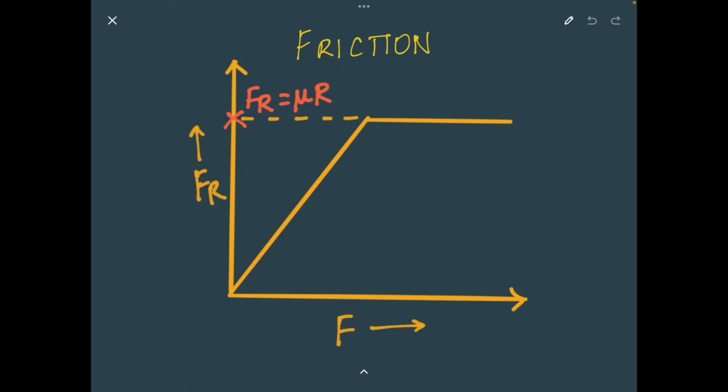Before we move forward with the more complex example, let me distinguish the behavior of the friction force in theory and in practice. We saw that the friction force developed between the surfaces will reach maximum and stay maximum after a particular applied force. However, this is applicable only in theory. In the real practical case, the friction force will reach maximum and after the body is in motion, the friction force will drop down from its maximum value. Okay, now let's move on to our second example.